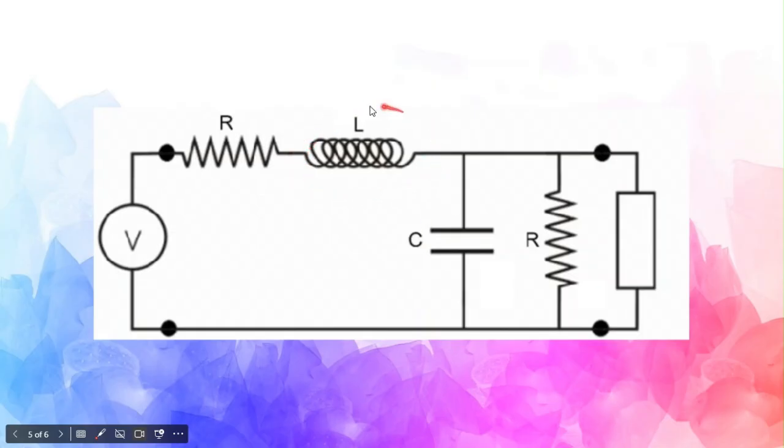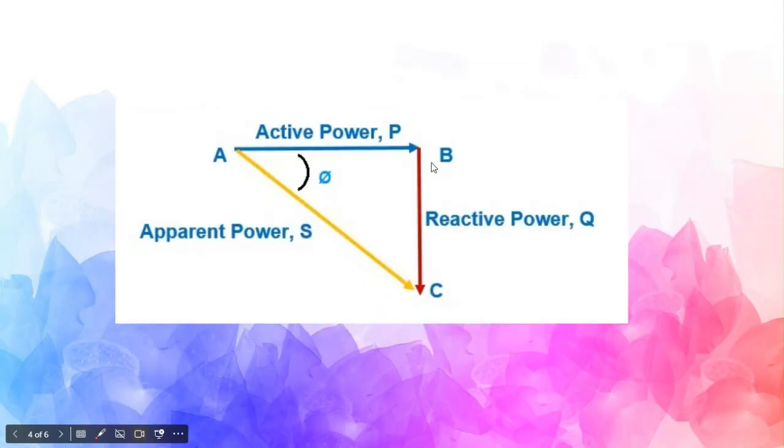So this can be reduced using capacitor banks. For example, if this phi, if we can reduce it to zero, to this value, where voltage and current both will be in the same phase, then I don't need this apparent power, and I can make this reactive loss completely zero, which is helpful for equipment sizing. For example, the transformer's KVA can be reduced up to this.